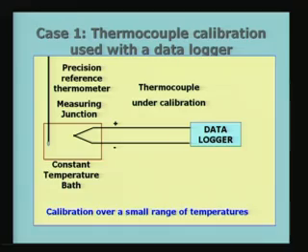If I look at the sketch here, this is the precision reference thermometer which is accepted as a standard as far as this particular calibration is concerned. So, I will take as truth whatever value of the temperature is indicated by the precision reference thermometer, which itself may be calibrated or certified by a standard laboratory. So, that is the way we are going to go about it.